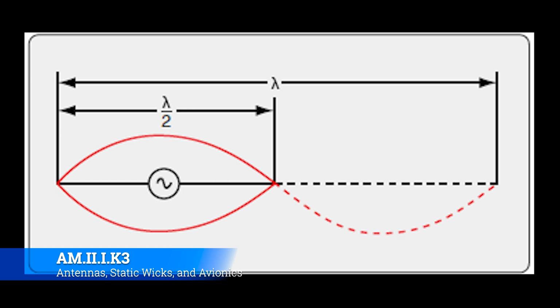And then you put capacitors in there, or a variable capacitor, to help self-tune as you change frequencies. As you go up in frequency, the capacitors react so that they can electrically lengthen the antenna effectively. And then as you tune it down, the capacitors operate in a way that electrically shortens the antenna and allows for an optimized transmission.